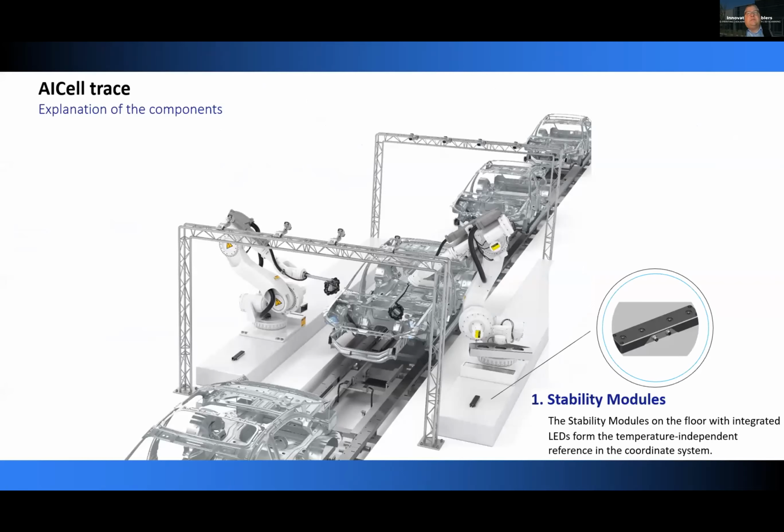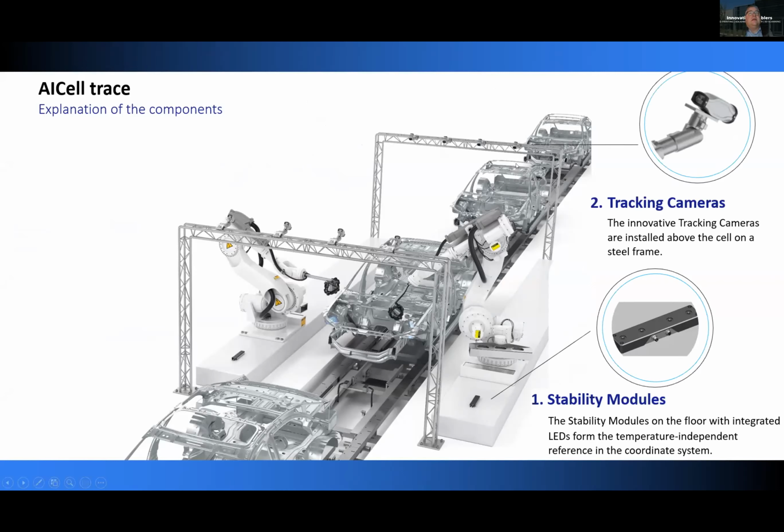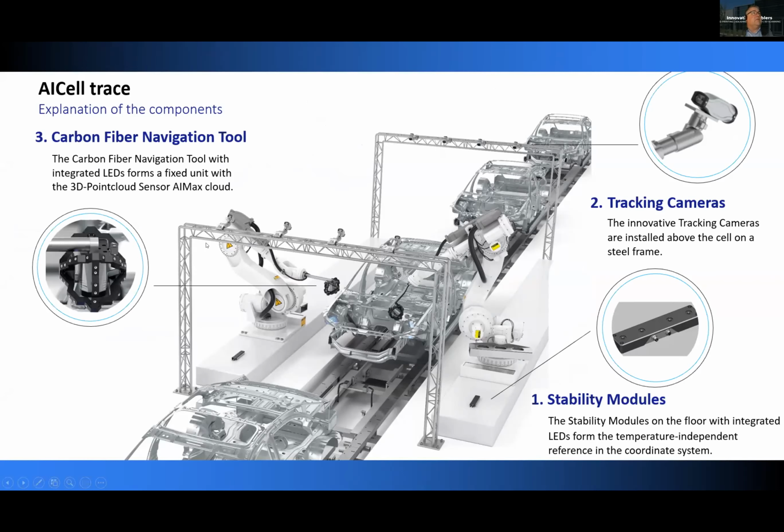And just a couple of the real important pieces that we're installing out there. Motion sensors, so that if there are vibrations coming through the floor, that can be compensated for. The cameras that I spoke about on a scalable network, and then a carbon fiber tool that we're tracking through strobed LEDs. So this actually is flashing lights at a very high rate that the cameras are picking up. And this actually becomes a calibrated CMM volume, roughly to about 100, 150 microns, depending on the size.